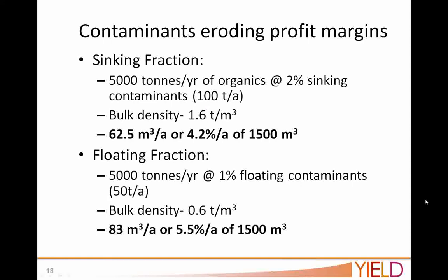You're going to release water from cells, and therefore you're going to decrease the total solids inside your digester. A fraction of this material floats, and a fraction of it's going to sink at any given percent total solids in situ. So the sinking fraction will effectively, both of the fractions, the sinking and the floating, occupy volume. So how it erodes your profit margins is that from day one, if you're not cleaning the tank inside, you're effectively losing digestion volume, and we sort of call it capacity degradation.